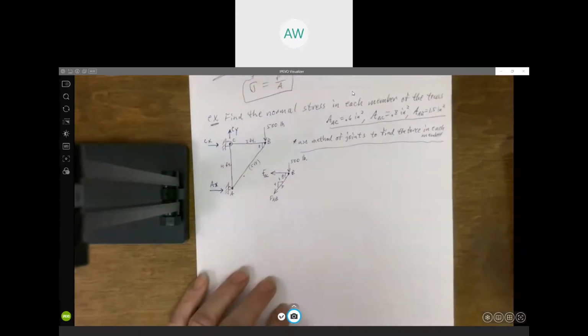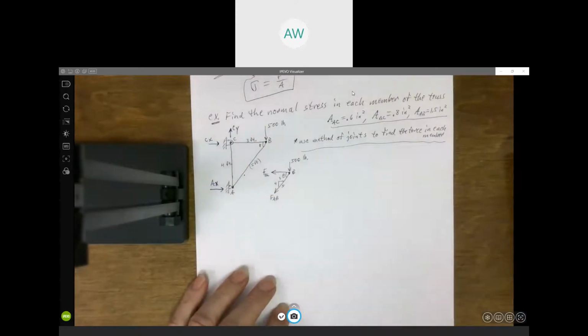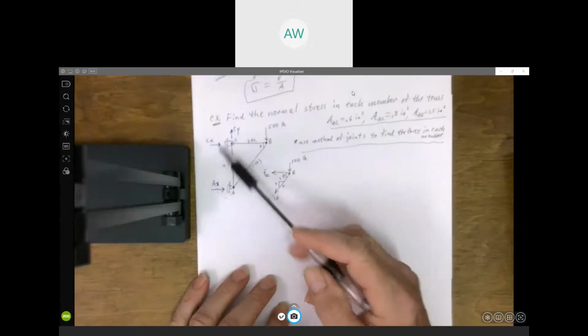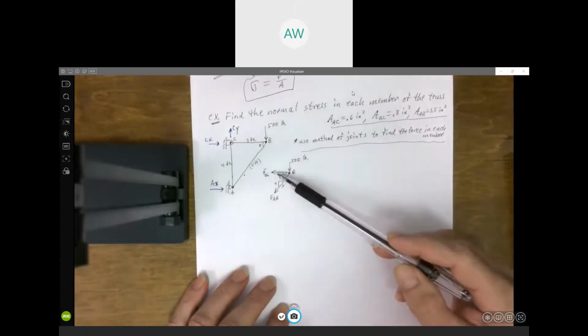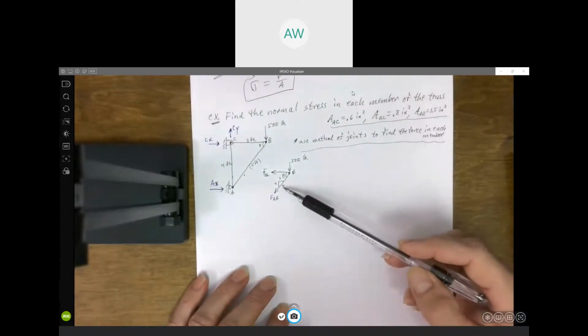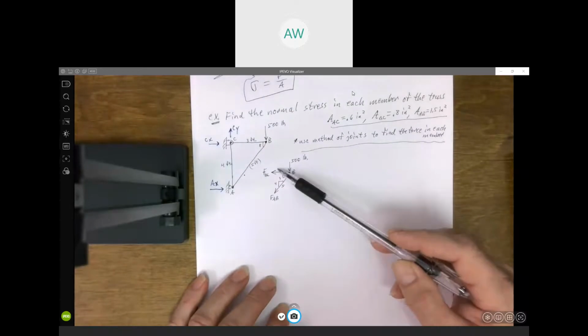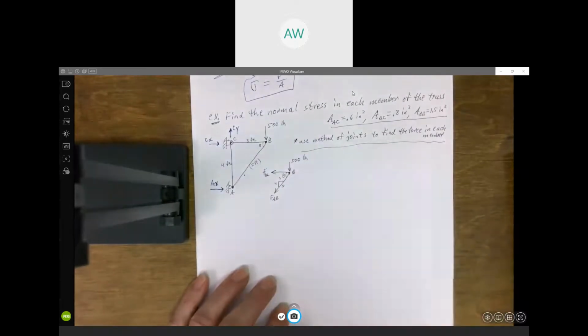All right, another observation here, sort of related to the previous question about whether it matters which direction I assume these support reactions. Technically, it doesn't matter which direction I assume for these two unknown forces either, force BC or force AB. But I always teach my statics students to assume the unknown members are in tension.